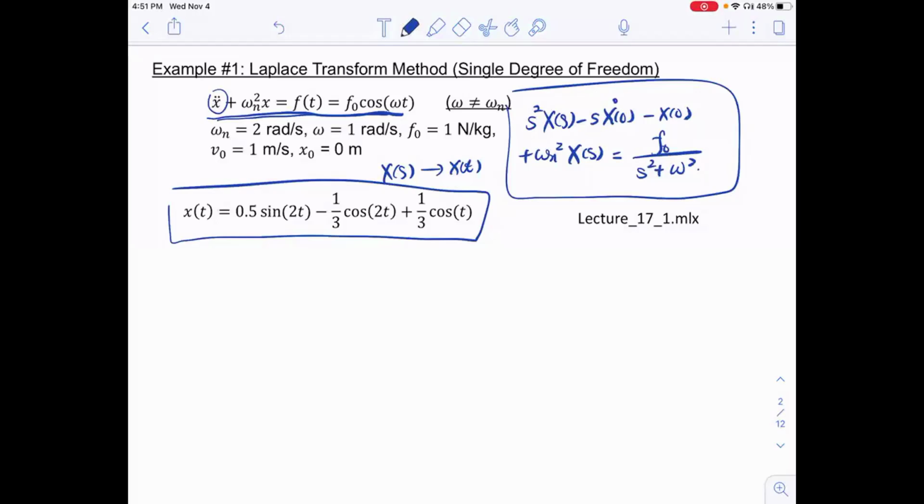First of all, we need to convert the second order ODE to state space. In order to create the state space representation, we need to create a state vector. Let's name this state vector y, and this y should have displacement and velocity in it. If you recall what we learned during the ODE45 lecture, the order of these state variables doesn't matter. You can put velocity first and then position. Here I just define the y in this way.